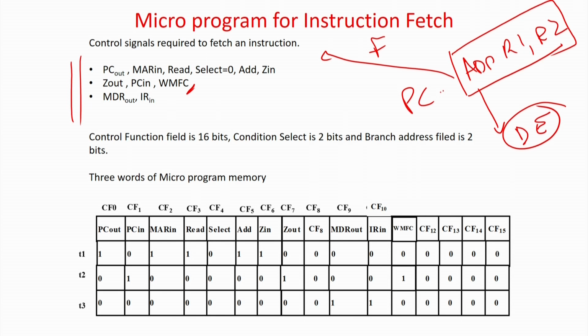So whenever you have to execute this instruction, say for example the program counter is fetching it, immediately the MPC will be loaded from the microprogram memory. Let us assume that is the microprogram memory, say it will go to 0 0 0 1 and 1 0. It will immediately make MPC equal to 0 0, which corresponds to the starting microinstruction for fetch, that is this one.